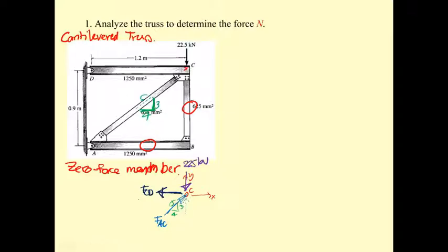That is the free body diagram of joint C. From the method of joints, which one should we use first? Summation of F sub x equal to 0 or summation of F sub y equal to 0? If you use x, you will get two unknowns and not get the result yet. So we put the first one as summation of F sub y equal to 0.